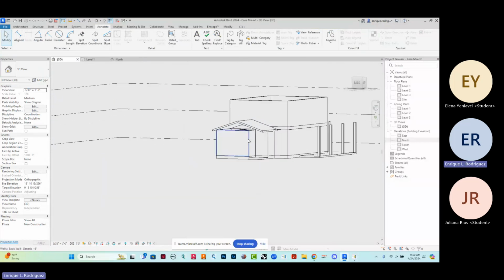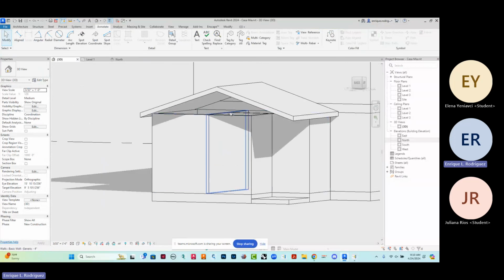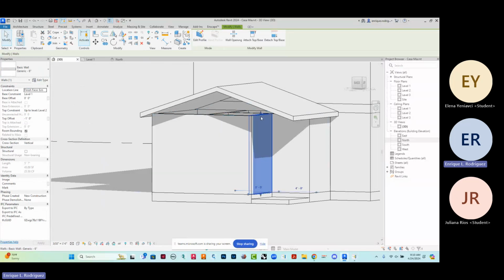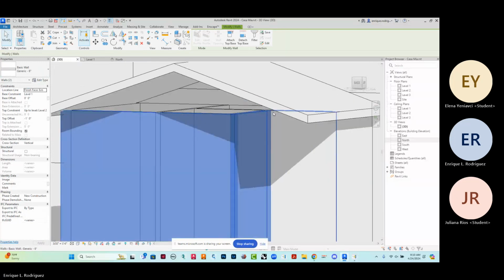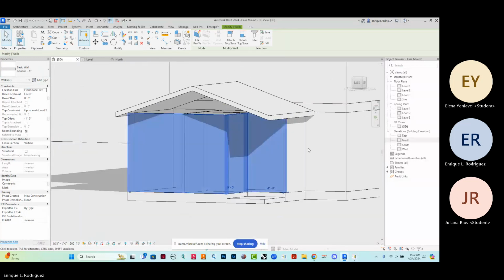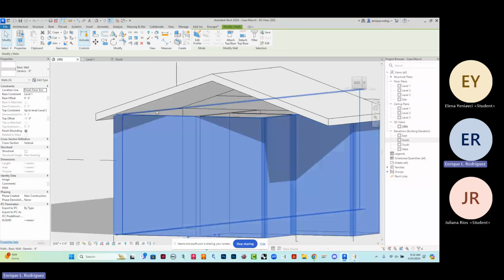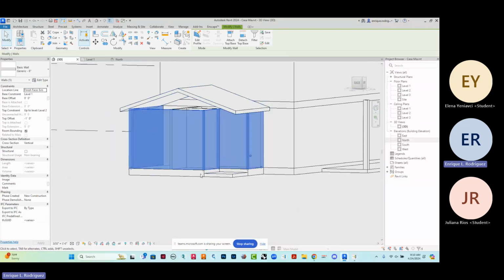The only problem I have is that my walls, I'm not going to worry about the interior walls. My exterior walls, I want them to extend up to the roof. So I'm going to highlight the walls, and I can do this in multiples. I hold the control key. I could even do it to this wall if I wanted to. Now this one's going to be a little unique because it extends through, but let's go ahead and do it at this point right in here.